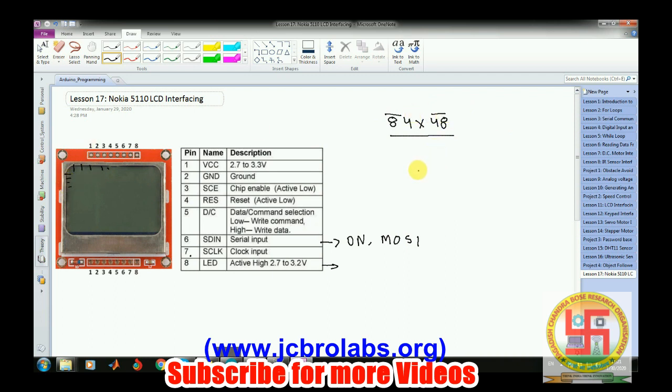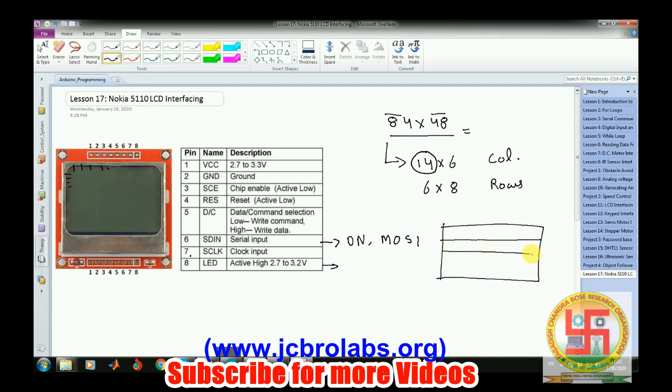Okay, and we can divide this particular row and column pixel configuration into words to display the words. So we can divide into 14 cross 6, with 6 pixels per column and 8 pixels per row. Here this 14 represents the number of columns, or number of characters which can be displayed in a row, and there are total 6 rows. So these 6 pixel columns are used to make a column, and vertically 8 pixels are used to make a row.